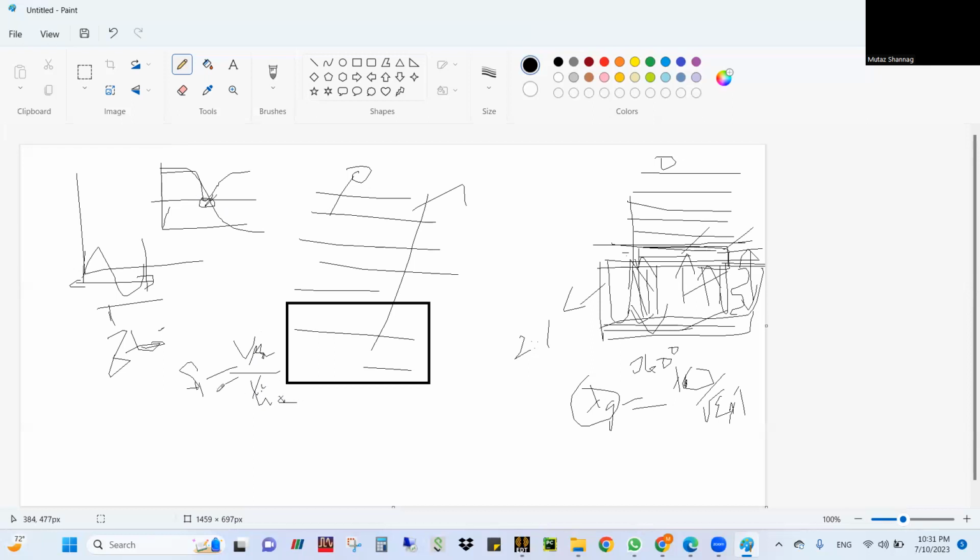So reflected means whatever is getting reflected. Incident means what is incident. Ideally, for an ideal reflector, whatever you impinge, it just reflects, right? So that is 100% reflection. What will you get here? You will get one, right? The reflected voltage is the same as the incident voltage, 100%, which is 1. If you take the logarithm of this, what do you get? 0 dB, correct? That's what you are seeing.